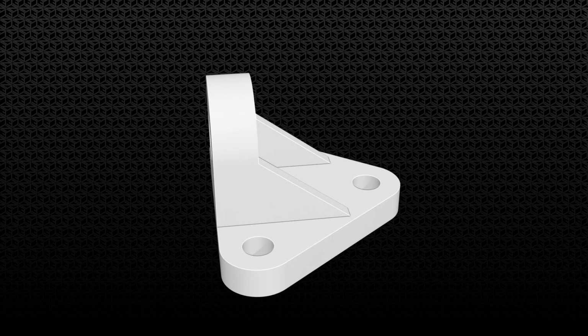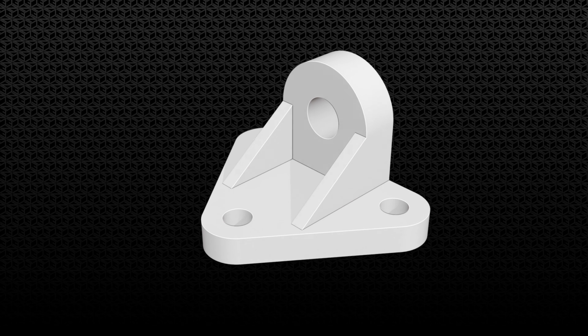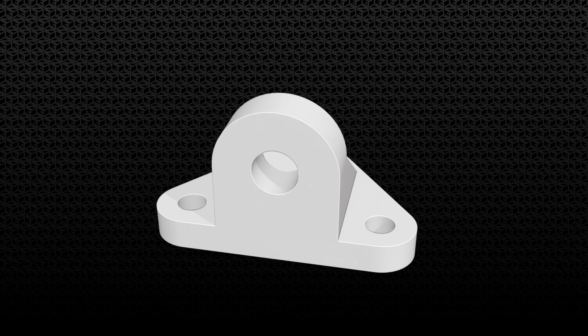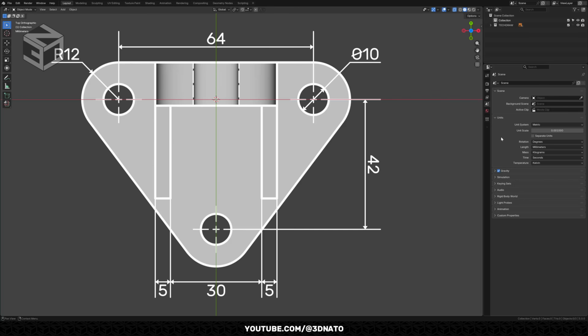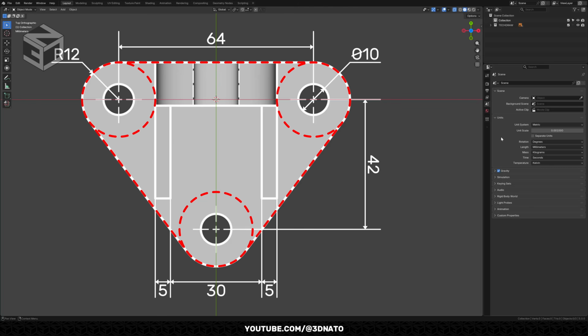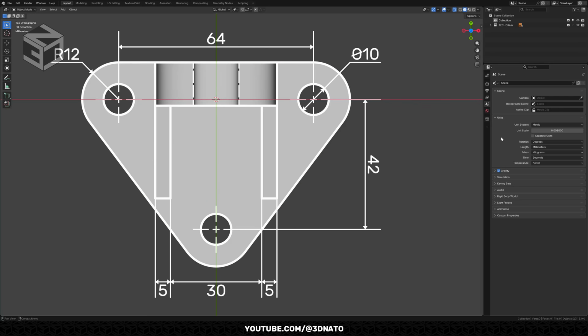In today's video, I'll show you how to add perfect tangents with precision drawing tools. I'm going to start by tracing the main outline of the top sketch. What I like to do is to break the sketch into basic shapes. Here we have 12mm radius circles connected by external tangents to create the outline, and inside each one there is a 10mm diameter circle to create the holes. So now we have a starting point.